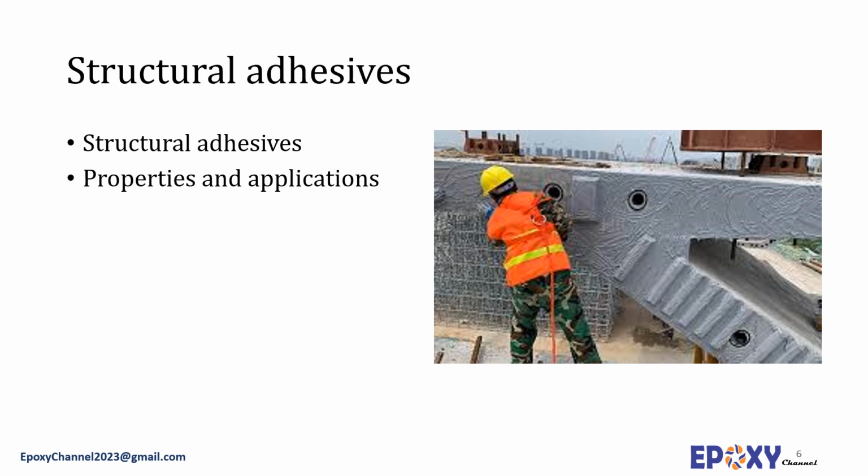Structural adhesives are usually solvent-free formulations, but sometimes sprayable solvent systems or water emulsions are used to bond substances to produce high modulus, high strength, often permanent bonds. Epoxy structural adhesives are capable of transmitting structural stresses without loss of structural integrity and are often used for bonding concrete to concrete or other substrates in civil engineering.